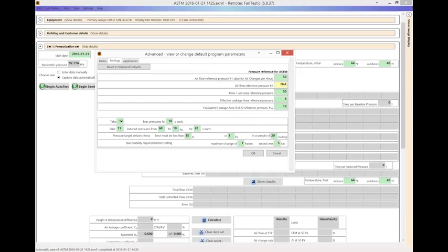So what I'm going to do is alter the parameters so that I can actually run a test and we can not sit here and watch this go for the rest of the webinar. So I'm going to tell it, instead of taking 12, to just take one baseline for 5 seconds. And if you're learning this, it does help to actually modify some of these things so you understand what the parameters are that you normally have. So I'm going to just tell it to take 3 points, all right? And I'm going to just reverse it so it doesn't get so loud too quick. I'm going to have it go from 20 pascals to 60 pascals.